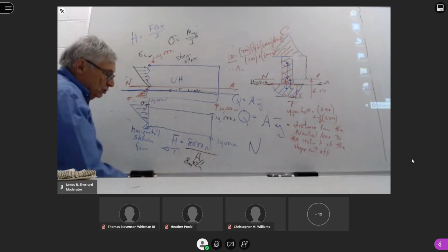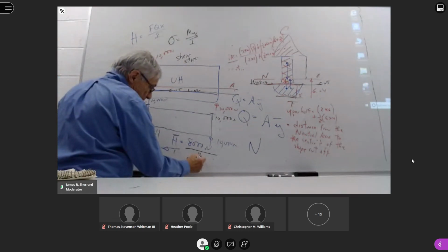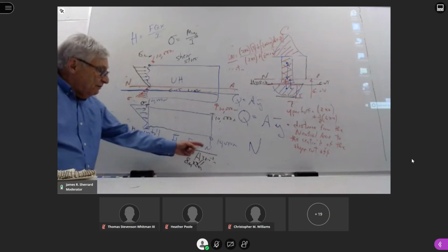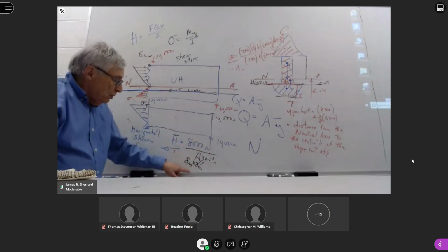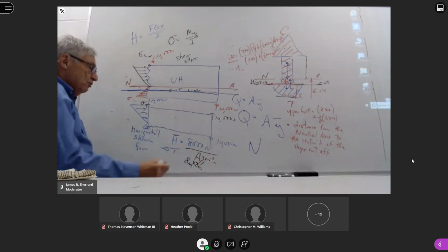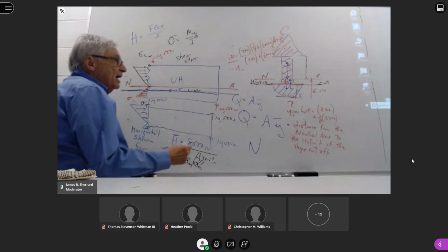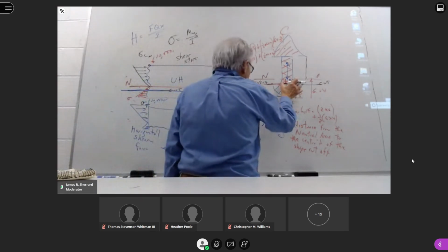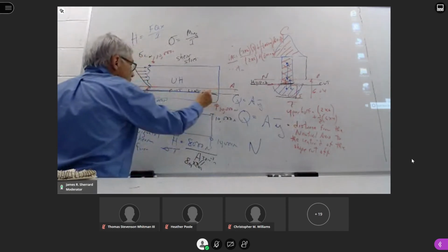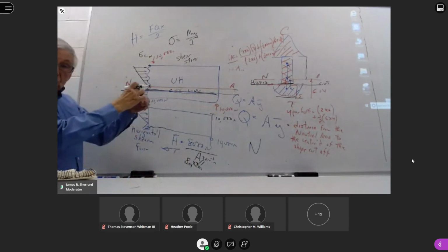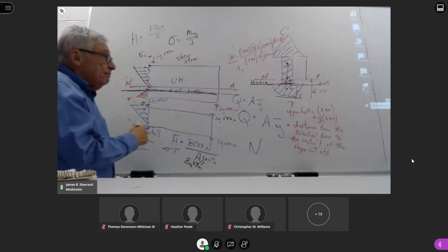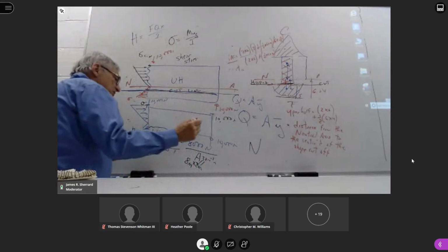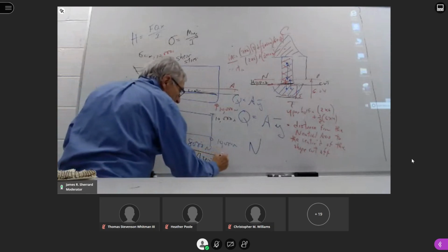Now you'd have to get units here, so we need to make this into meters, so this would be 2 times 10 to the minus 2 meters, because we need to have newtons per square meter. So if we divided this force by the area of this cut plane. You see it here like this, over here, you see it like this. So it's actually a rectangular plane that's 2 centimeters by 8 centimeters long. And if we divide the force by that, we have